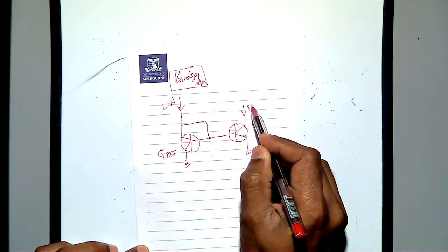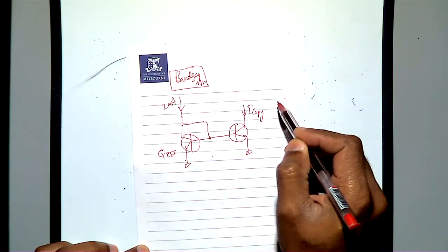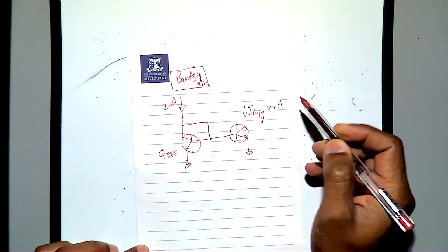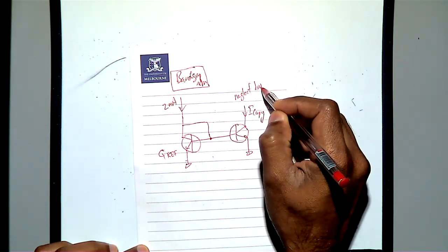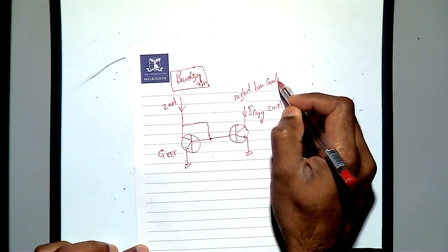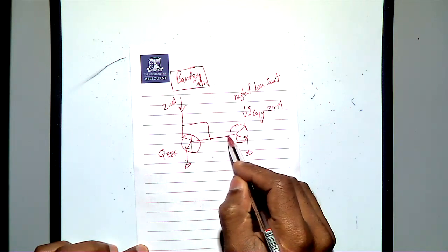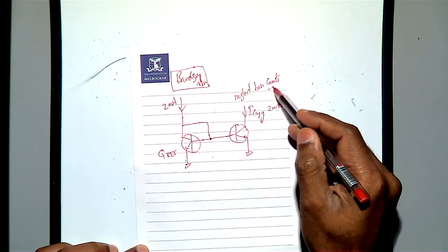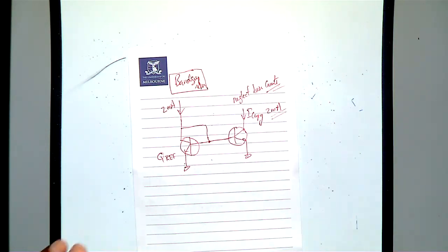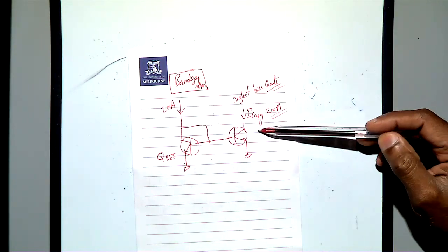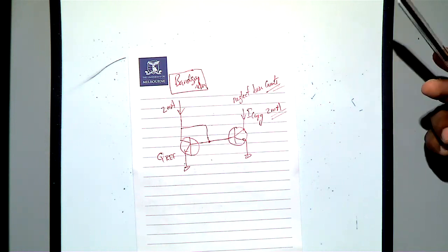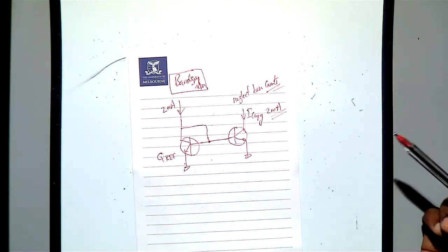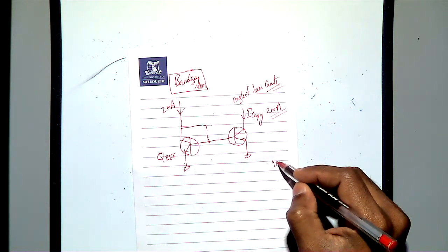and then we are getting I copy, and this is 2 milliamps provided we neglect base currents. This base current we are neglecting, so we get around 2 milliamps. If we connect one more transistor here, we can add up 2 milliamps: we can make 4 milliamps, 6 milliamps. Now maybe I need only 1 milliamp.